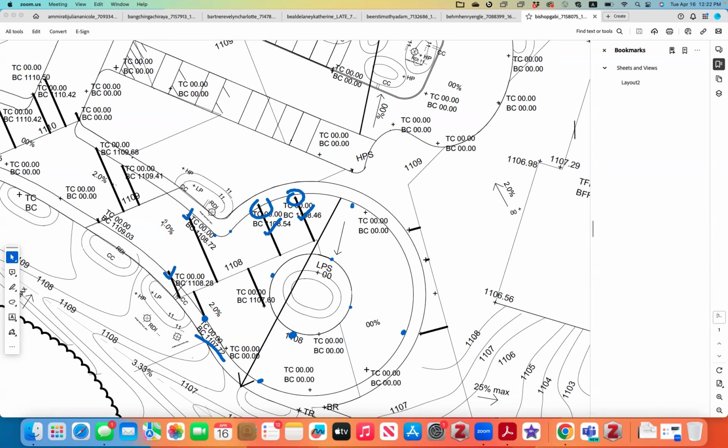And my leader line, I would not do it from the cross sign. I would do it from exactly the same spot on the curve, but they're close enough. Okay, they're close enough. So not the cross sign. It should be the location on the curve. So in the future, make sure you start with the curve location instead of the cross sign center. But it seems like the spot elevation calculations are on target. Okay, so that's about the spots.